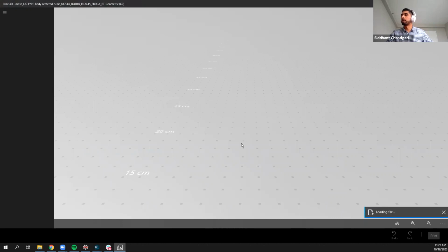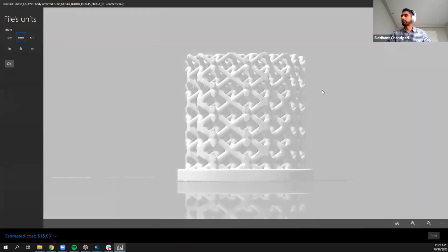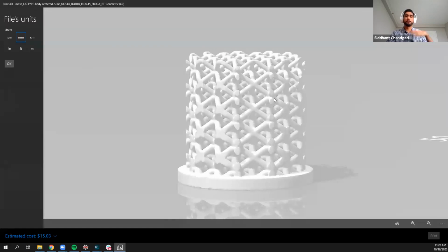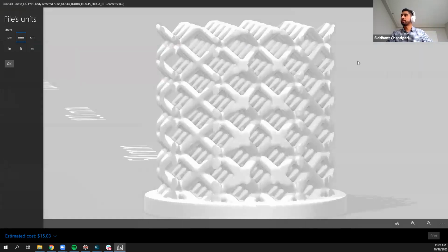It'll just be a simple mesh file consisting of the lattice structure, and we can get this ready to print. And if we run this passively, then it's much smoother. We'll get all these mesh files and then we can just print them on whatever 3D printer that we choose. And for each of these, in this case, I labeled it by a certain unit cell size, the rotation, the initial relative density, and final relative density for this ramp structure.